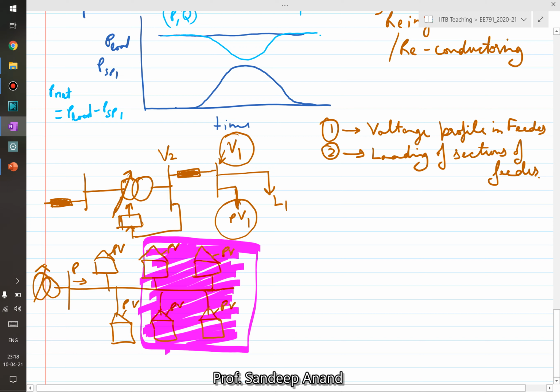As this cloud is moving, if it covers, let's say, 40, 50, 60% of the houses, then suddenly the power being produced by those photovoltaic panels will get reduced, and that would create a much bigger perturbation in the power compared to the perturbation created by the switching of loads, because it's more synchronized.